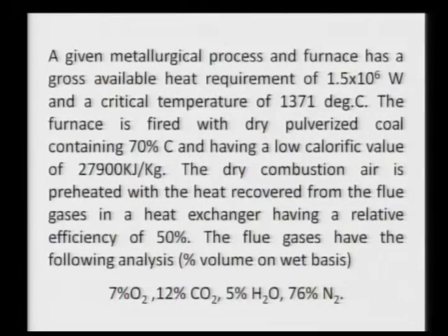Point number 2, it is said in this particular problem that coal has a low calorific value of 27,900 kilojoule per kg. That means that here the calorific value of the fuel is given by considering the gaseous state of the products of combustion, for example, C to CO and H to H2O vapor. That is important, because while calculating the heat taken by the products of combustion, the standard state for input and output must be the same, otherwise there will be an error in the solution of the problem.